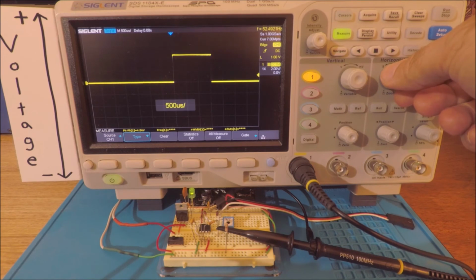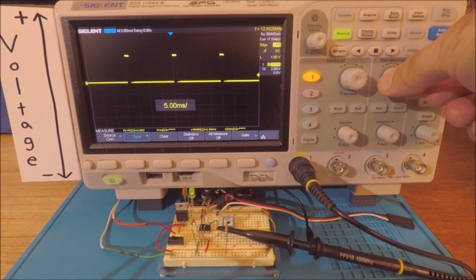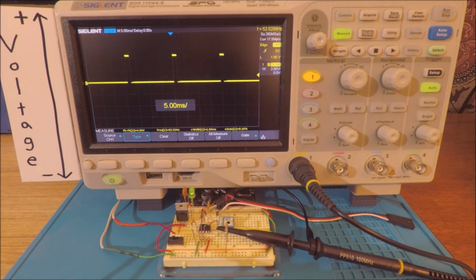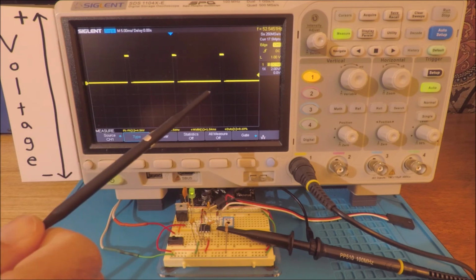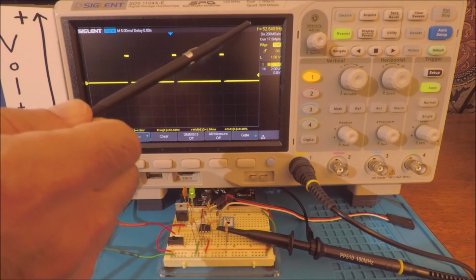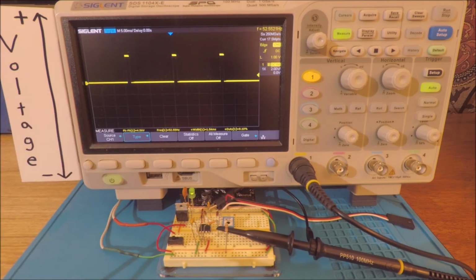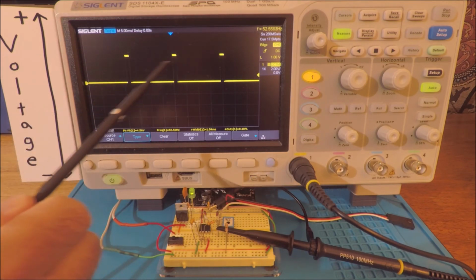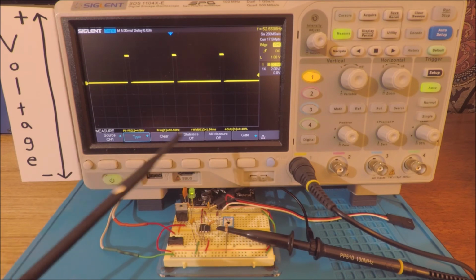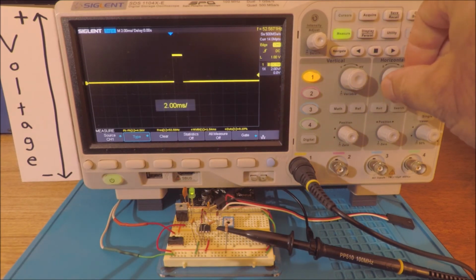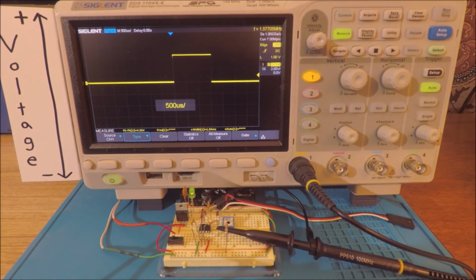We can adjust our horizontal scaling so that we can view that pulse as well as the next ones. So on the screen right now, because we have multiple pulses, the oscilloscope is reading off that we have a 52 hertz signal, and it's in fact measuring the width of one of those pulses as being 1.5 milliseconds wide. And let me readjust the horizontal scaling so we can see that width of just one of the pulses a little bit better. So we have a 1.5 millisecond wide pulse.